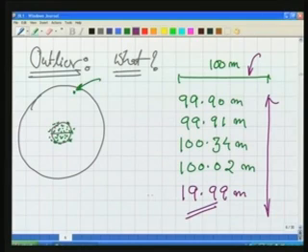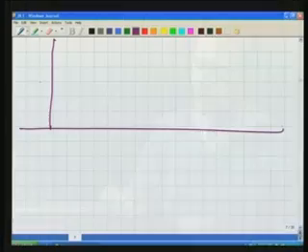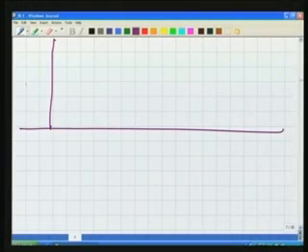So, this kind of observation we also call an outlier. If there are outliers in our observations, we need to reject them, we need to eliminate them, so that our observations are purer. I will give you another example of how you can see the outliers. For the same length, if I plot the length here, let us say along this ordinate we have the values and 100 meter is around here.